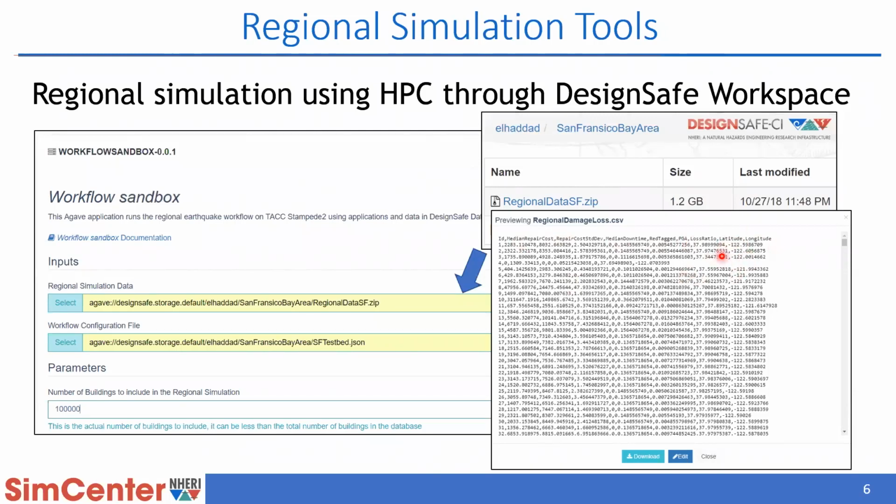And this location, as we will show later, turns out to be very handy, because once you import this file in GIS tools, you can have the spatial distribution of all of these results, because each one of these points has a location. Then you can start doing spatial joins, and you can take this data and join it to other layers of data you have, like the building footprints or the parcels. And we'll see this in the demo in a little bit.